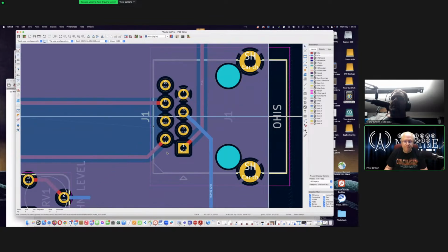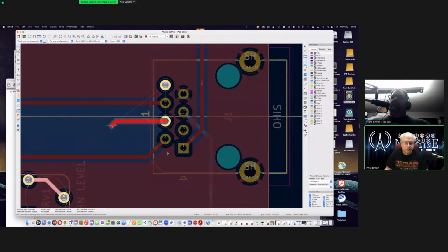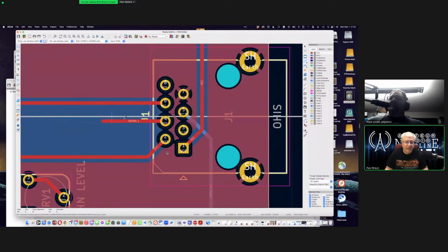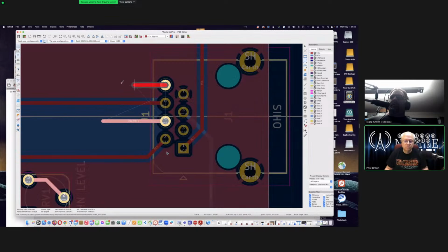Yep. Okay. Then what I'm going to suggest is go back to the red layer. Now, drag a trace from pin 4 straight to the left. And make it straight. Don't make it have a little dogtail at the end. Terminate it right there. Double click it. Okay, yep, that's fine. Do the same thing with pin 8. And terminate. Yes, exactly right there.